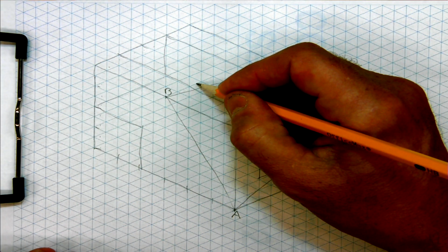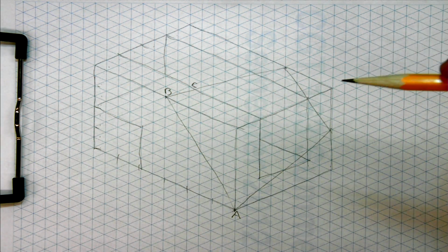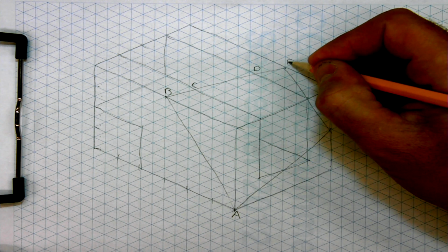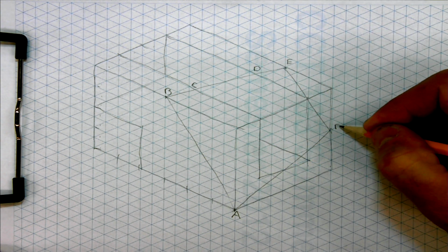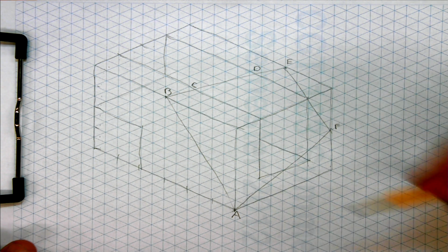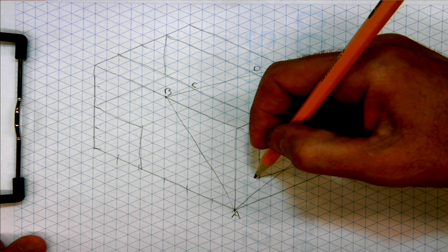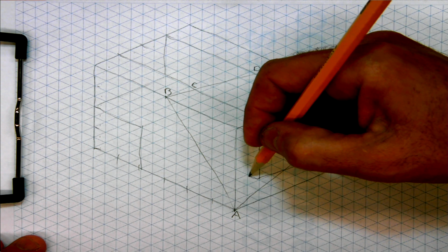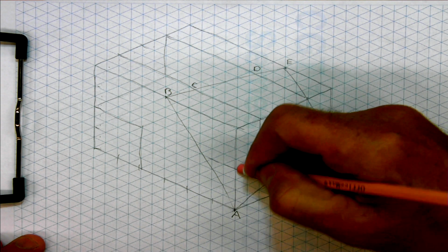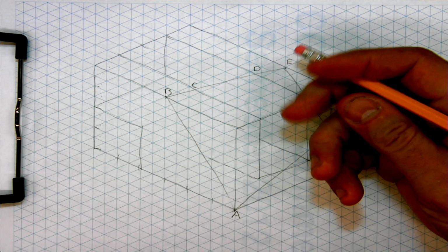So I'm going to name this point C here, okay? And then we'll name this point D, E, F, and go back to A, okay? So with that said, you know that this plane, just like this edge here, this one here goes back, okay? You're starting at this corner, it goes back into here as a hidden feature. So I'm going to put this thing as a hidden construction. Now notice on isometrics, you don't put in these dashed lines, but I'm doing this for construction purposes.